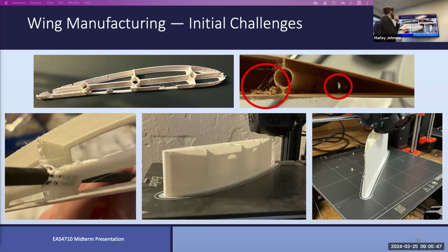In terms of how our prints evolved, we first tried one with regular PLA. One thing we were struggling a lot with was the thermal behavior, because of how the G-code laid up the PLA on the skin and the ribs. We got some thermal contraction and the skin was breaking up. We were also trying to deal with how to attach different segments.